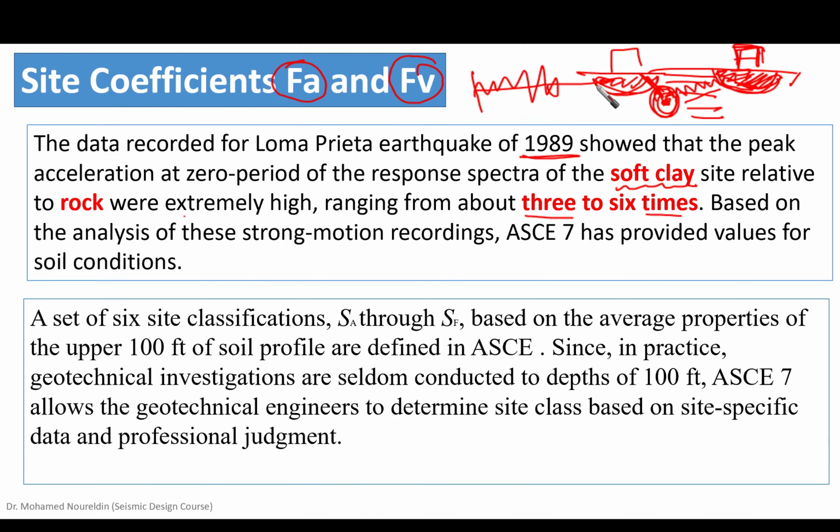But they found that the soft clay is magnifying the earthquake waves like 6 times. So this means that we need to consider the soil condition underneath the structure. Based on the analysis of these strong motion recordings, ASCE has provided values for soil condition. Now we are taking into consideration the soil condition.